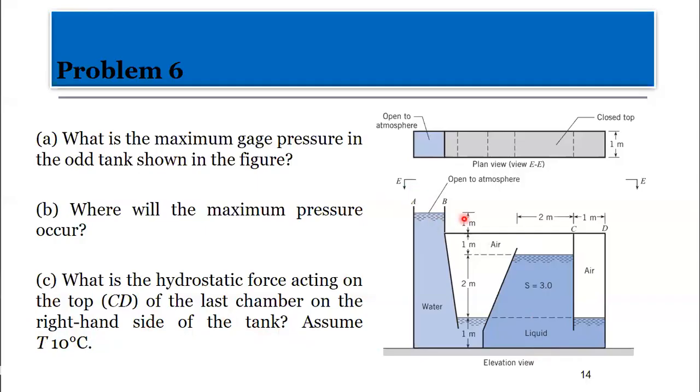Now pay a closer look at this diagram. You did technical drawing or engineering drawing. Over here, the tank, this is the front view, or the side view. At least that will give you the detailed front characteristics of the tank. You see the view they've indicated here, view EE. The arrows are directed downwards on top of the front view that we are looking at. So if you look at view EE, you are going to see the top view, which is more or less like the plan view.